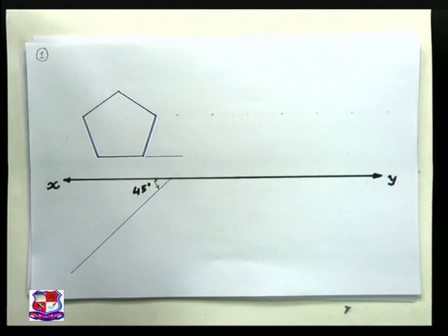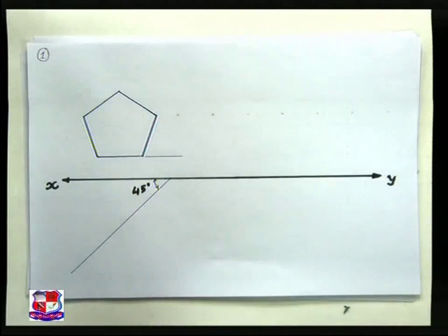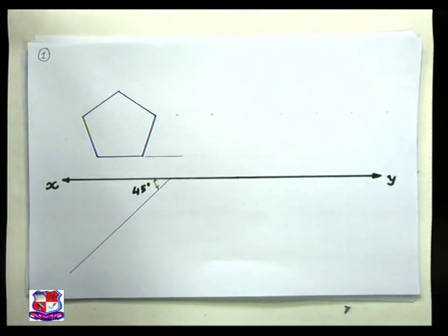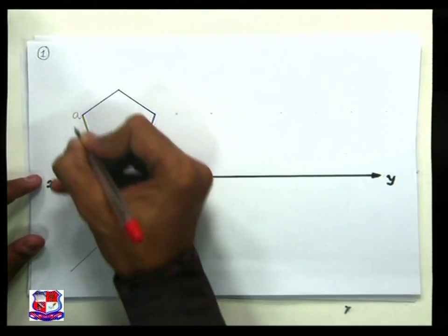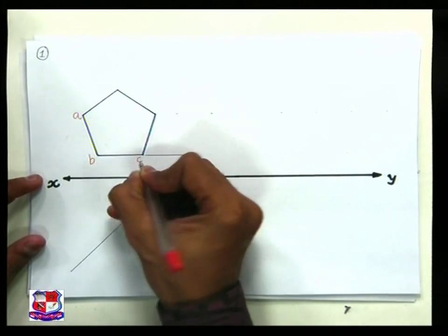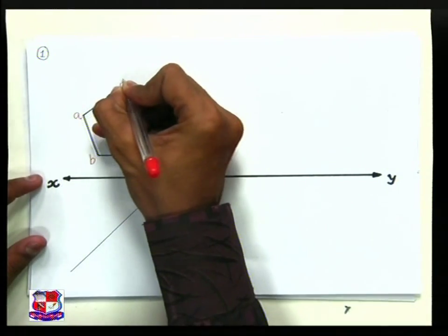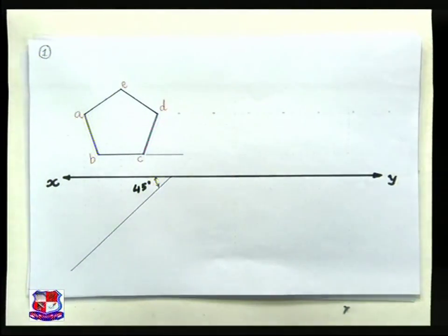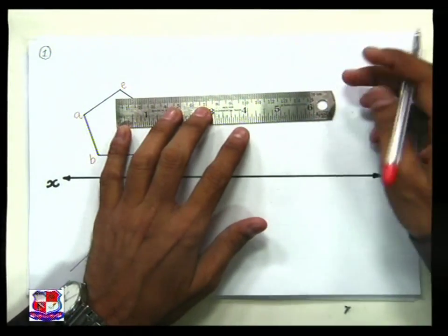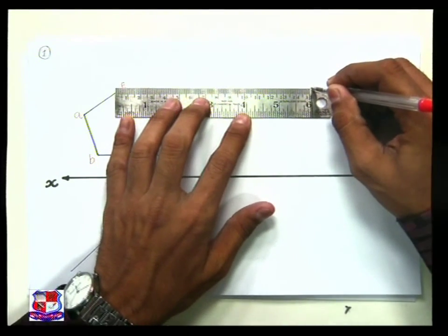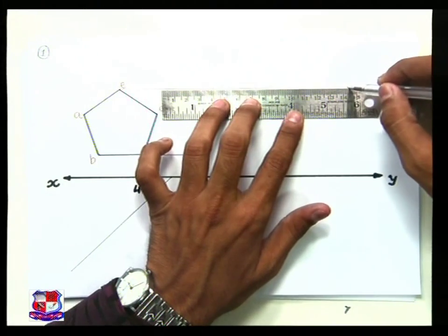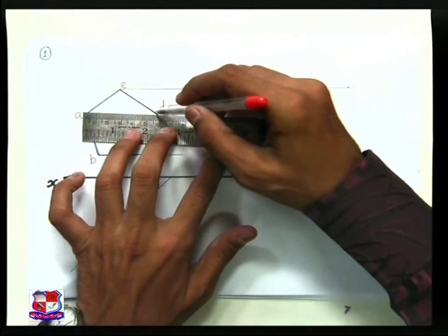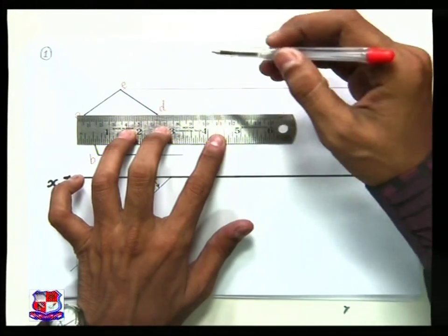Now after that take projections from these 5 points. Name the endpoints. So this is endpoint A, B, C, D, E. As it's a side view, you can name them with dash or 1 as per convenience. From all these points take projections like this. Horizontal line from point E, horizontal line from point